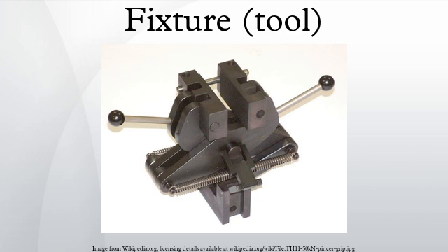Types of fixtures. Fixtures are usually classified according to the machine for which they were designed. The most common two are milling fixtures and drill fixtures. Milling fixtures: milling operations tend to involve large, straight cuts that produce lots of chips and involve varying force. Locating and supporting areas must usually be large and very sturdy in order to accommodate milling operations. Strong clamps are also a requirement. Due to the vibration of the machine, positive stops are preferred over friction for securing the workpiece. For high-volume automated processes, milling fixtures usually involve hydraulic or pneumatic clamps.